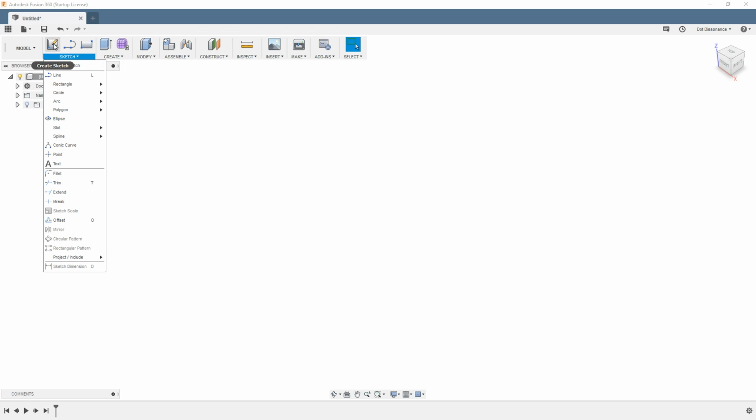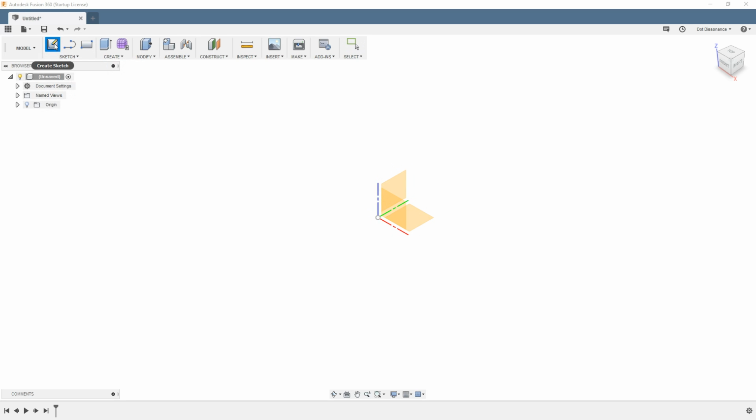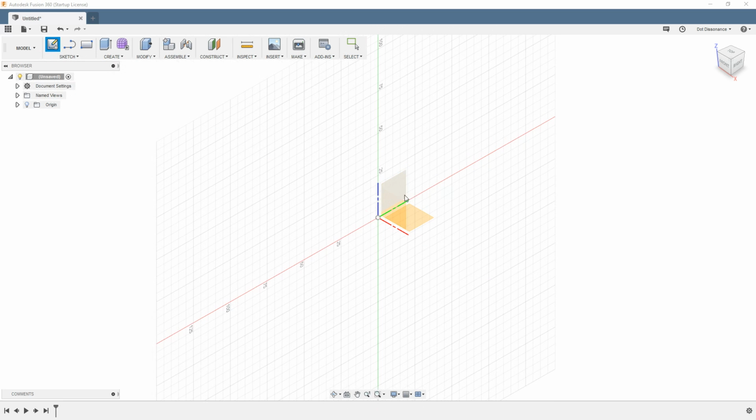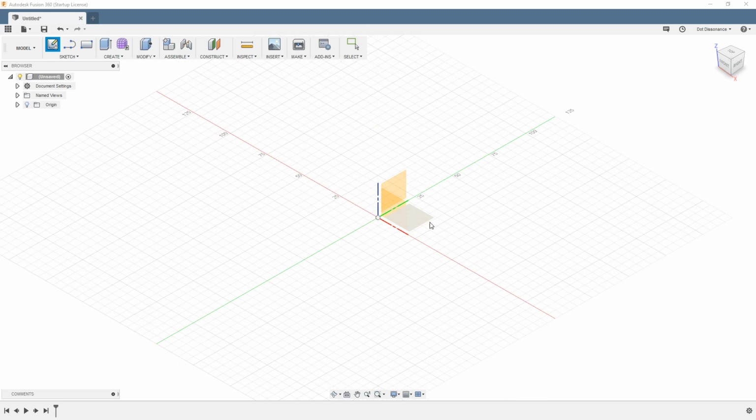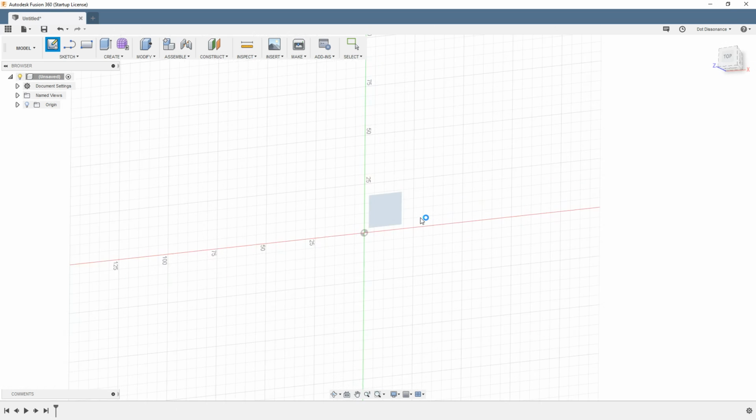Okay, so just watch for a second here. So I click on this. It's depressed. It's like a toggle. It's in. So now it's like half a sentence, saying I want to go to the sketch environment, and that's half the sentence, on one of these planes. As you can see, after I click this, our plane system shows up. Okay? So then I can click on the XY plane, for example, here.